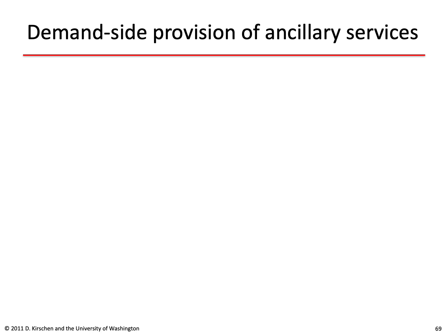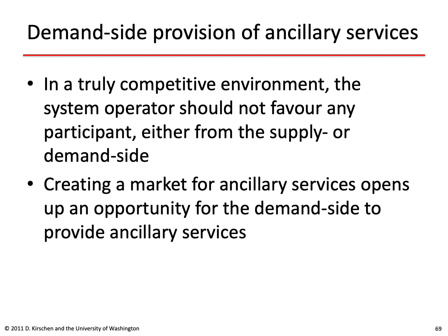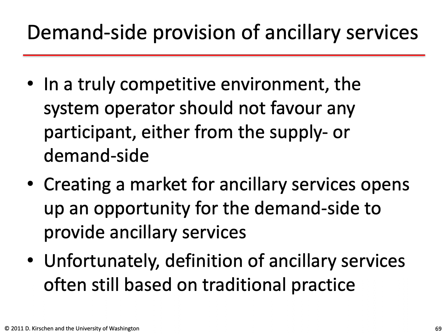I would like to discuss briefly now the provision of ancillary services from the demand side. Now, in a truly competitive environment, really the system operator should not make any donation in favor of any type of participant, whether they are from the supply side, the generators, or the demand side, the consumers. And therefore, creating a market for ancillary services opens up an opportunity for the demand side to participate and provide ancillary services. Now, that would be great, but unfortunately the definition of ancillary services are still very much based on traditional practices. It would be nice if that could change.